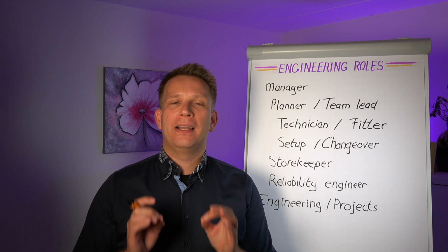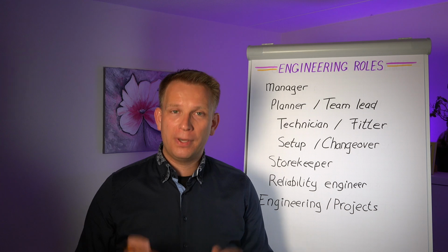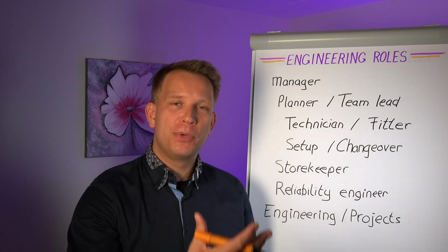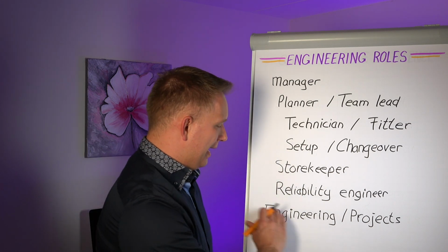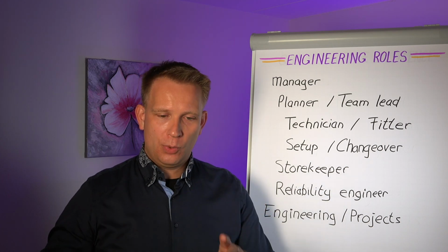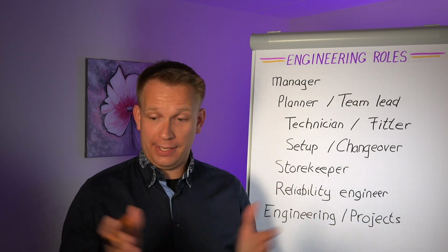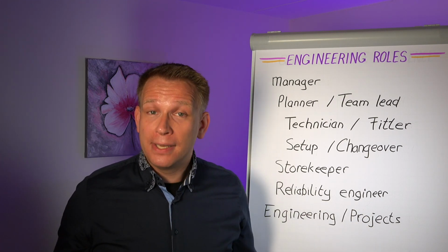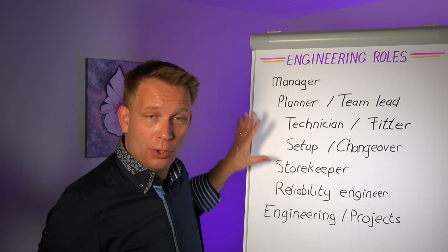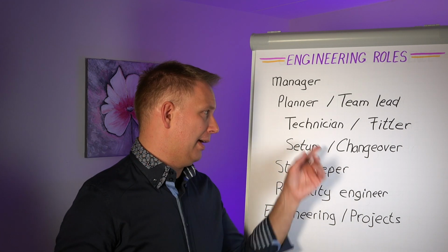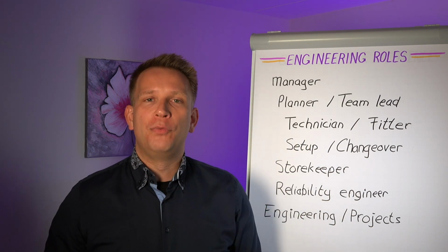And I know that that line gets blurry in practice quite often, but this is important to know on an organizational scale. So when you put a new machine into your factory, it belongs to your engineering and projects department. And only when you're happy that it runs as we predicted, we have all the maintenance plans, right? That stuff all needs to have been set up already. People are trained, operators can work it, our technicians can fix it, can repair breakdowns.